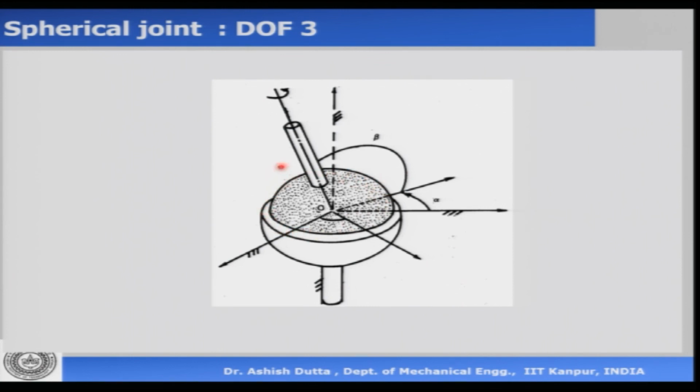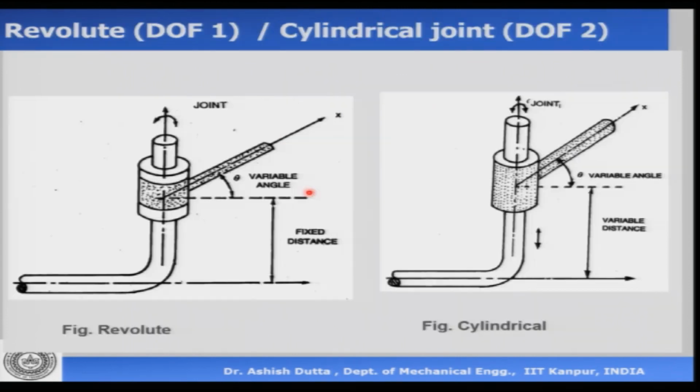So very rarely would you see a robot which has this kind of joint. And 99% of robots have revolute joints, essentially because each joint is connected with a motor. There would be a motor here which is going to actuate this joint, and each joint would have one motor with its own controller and sensor, with closed loop control.